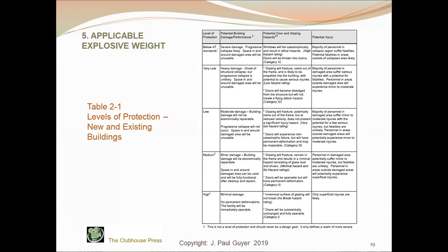The term progressive collapse is worth a little comment here. It's a concept that is being integrated into the design of buildings that potentially are targets of terrorist threats. What it means is structurally designing a building not just to withstand the static loads and the seismic loads and the wind loads, but also explosive loads.